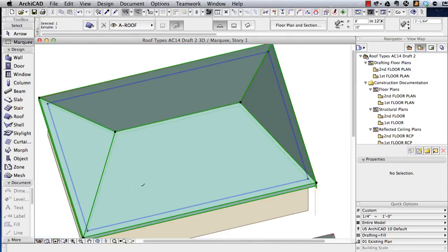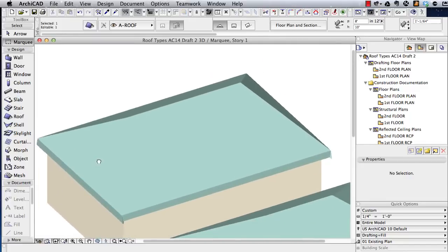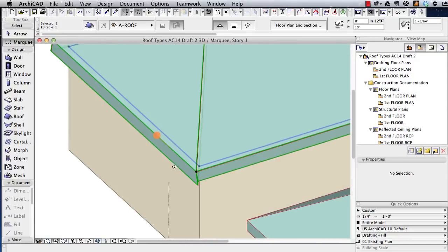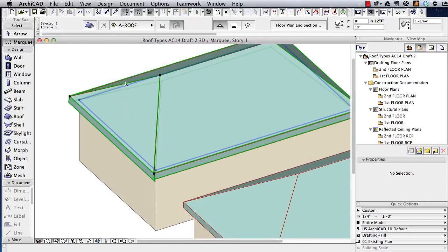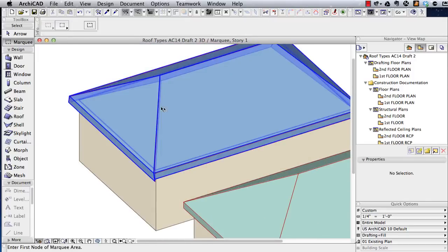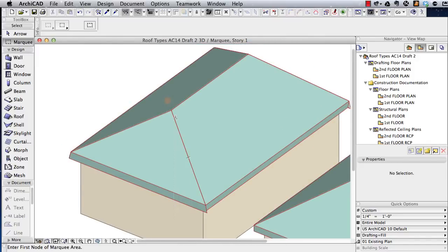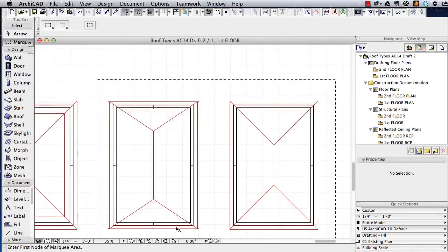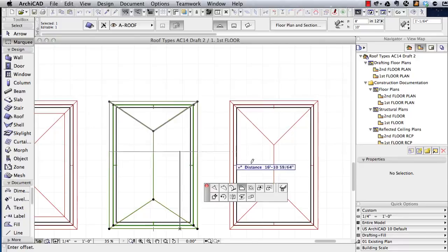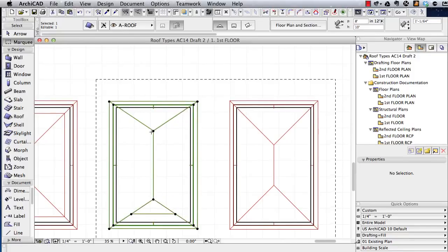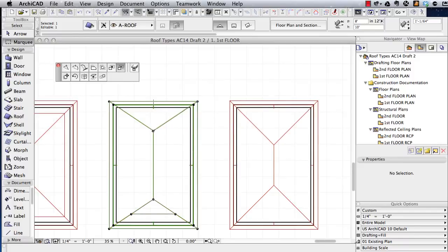Now we still have a little bit of an extra piece here that would need to be cleaned up using another method, either a solid element operation or changing the edge from a vertical fascia to one that was perpendicular or horizontal might work. But let's look at the other issue, and actually interesting, it lost the hole when I did that. I hadn't noticed that before, so let's go back and recreate that hole. So we'll do the subtraction here. And again, subtract from this side.